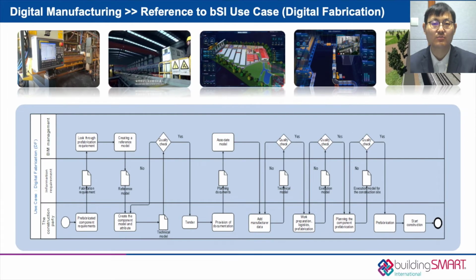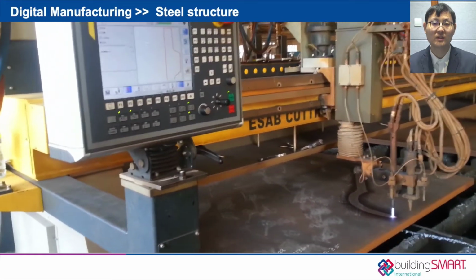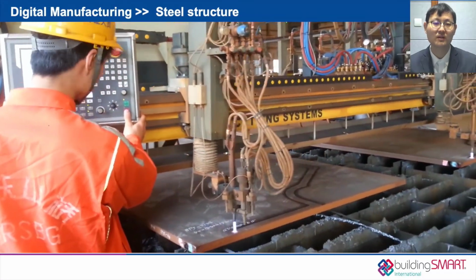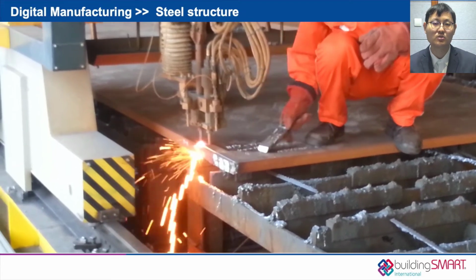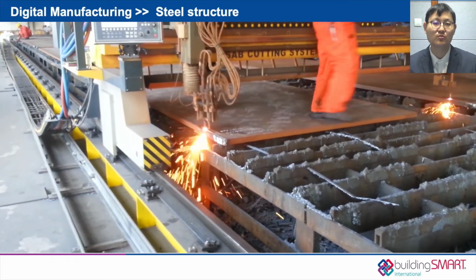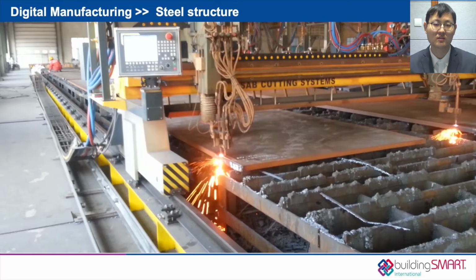In the digital manufacturing and production prefabrication of the project, we adopted the workflow from BSI use case, and based on openBIM, we realized the digital manufacturing of steel structures and steel rebars, the production of prefabricated beams and prefabricated components, and the integrated construction of bridge assembly. For steel structure manufacturing, we applied ANSI manufacturing module to add manufacturing information to the BIM model. The CNC manufacturing program can be generated, and it was directly recognized by the CNC manufacturing equipment to realize the digital manufacturing of the steel structure.